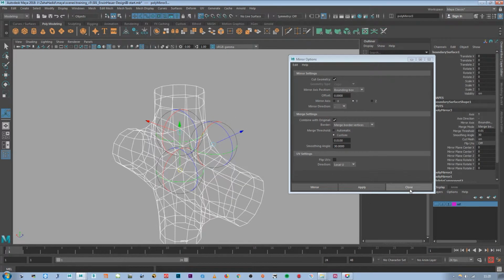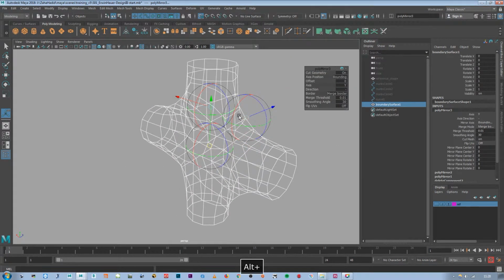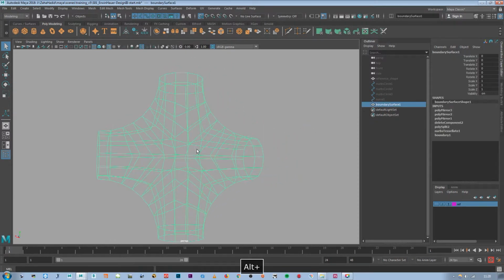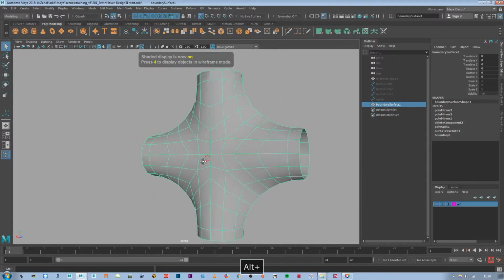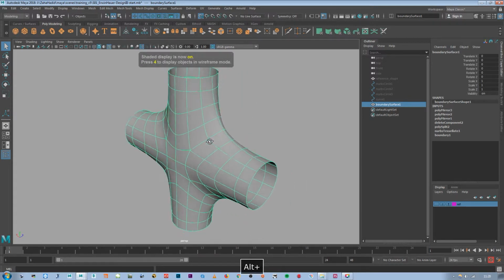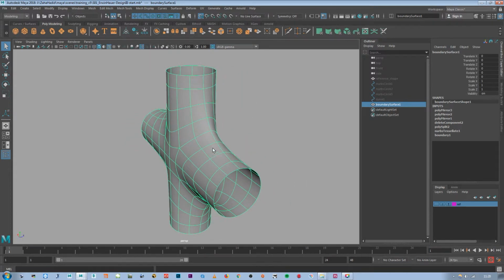Perfect. Okay, so we don't need them more. These are all surplus requirements. So if we click off and right click, click object mode. So now, in press 5, we have our beautiful shape, and if you press 3, it's short, 5 and 3, beautiful smooth object. So now let's give some thickness to this, so it's not paper thin.